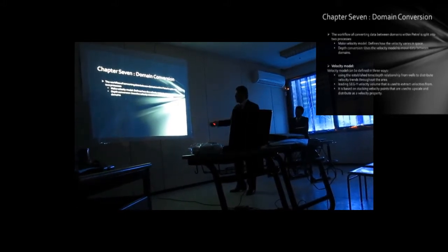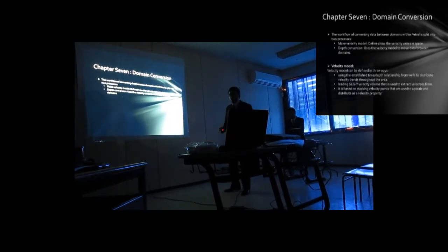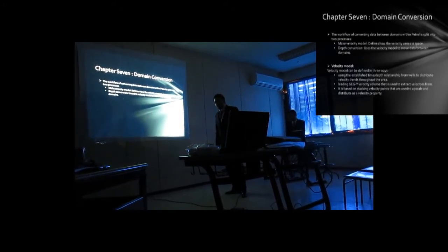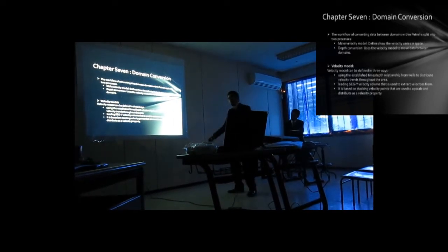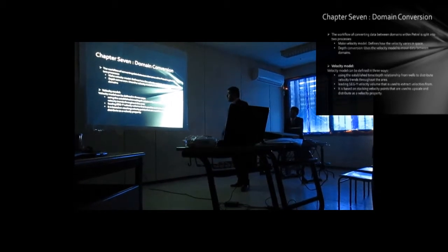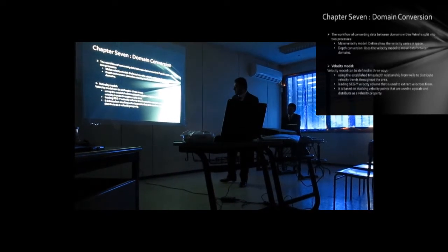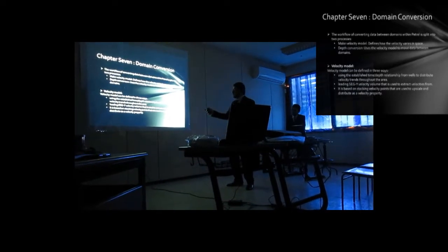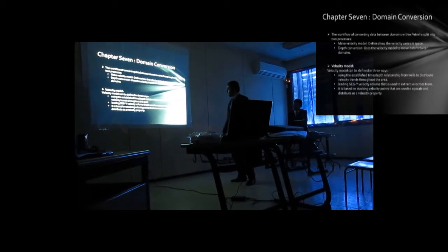When you build the velocity model, you can convert almost everything in your project from time domain to depth domain. The velocity model can be defined in 3 ways. Using the time-depth relationship from wells to distribute the velocity trend throughout the area. Loading a SEG-Y velocity volume that is used to extract velocity from.